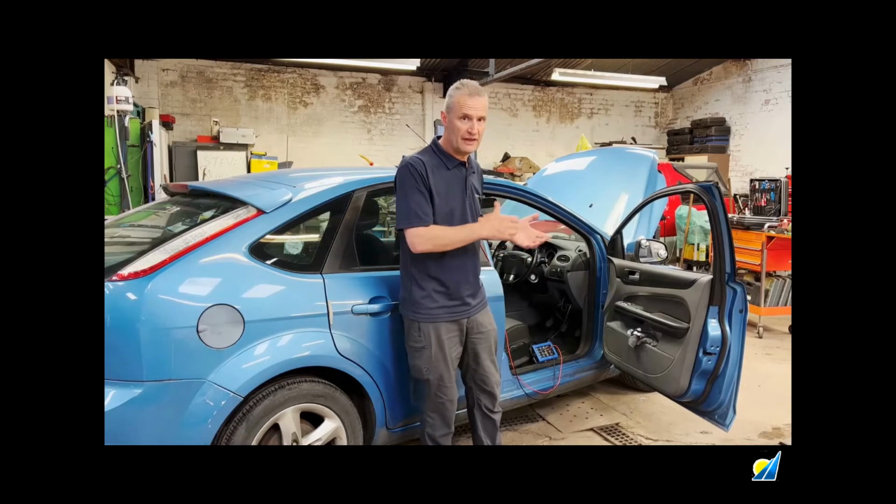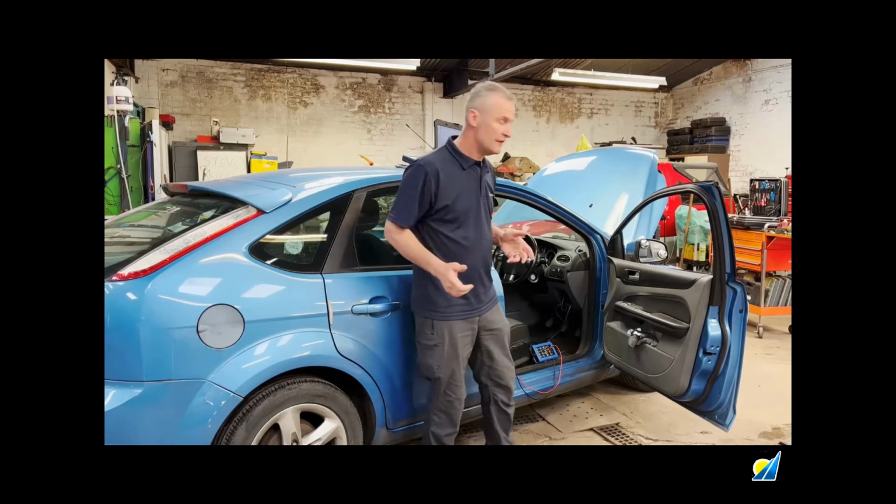So to try and simulate that, we'll graph the resistance of the 60 ohm CAN network. And how we'll do that, we'll use the Pico breakout box. The vehicle battery is disconnected. We're only using the breakout box as a pass-through, purely for convenience. And we'll start moving the vehicle.